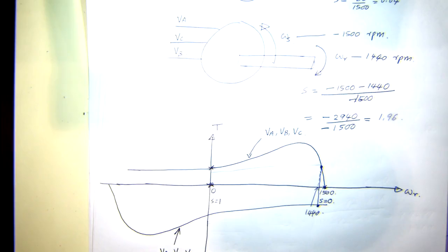Any questions in relation to this braking method of induction machines? Yes? Just one question. A plugging brake, when you reverse polarity to a vehicle... Yes, yeah. Say if you did it with contactors and you didn't have a VFD or anything, does it pump that current back into the grid, or do you need braking resistance?